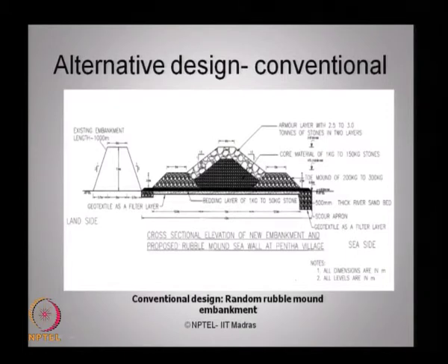So, this is a rubble mound conventional type of construction which offers a very high degree of rigidity, which does not suit a specific site where there is already a high pore pressure in the soil. This pore pressure is because of the soil erosion, the entrapment of water and the high level of sea rise in the specific site.